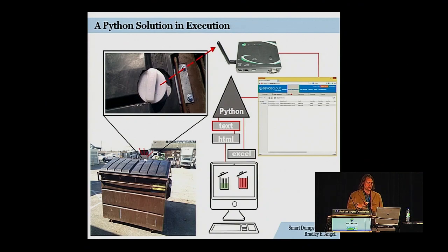So this is the kind of schematic we came up with. The sonar talks to a gateway. I don't know if anybody's used these wireless systems, but the sonar talks to a gateway. The gateway puts it on the cloud, and then from the cloud, my student worker Dylan actually wrote a Python script that would retrieve the information from the cloud, and then it would deposit it in 2 spots. It would put it on a text file for me, and then an Excel spreadsheet, so we would have a record of every sonar reading.